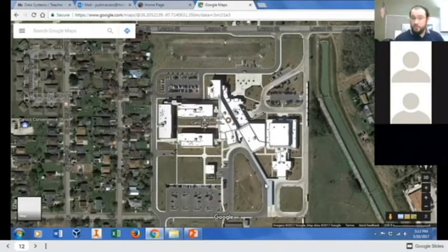All the county drainage ditches that you see and those large ditches between the two counties over in Mercedes, that's designed, I think, for somewhere between a 40 to 50 year storm. So a fairly rare storm, maybe one that you would only see once in a lifetime.